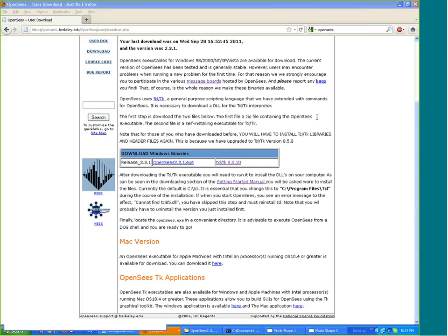Then the next question I have is from Andrew. I noticed the end conditions of the elements are not explicitly defined in the file. Is that part of the different elements' commands? Yeah, end conditions by default are rigid. So if you want to make a pin, then you have to use the equalDOF command. All ends are rigidly connected to each other. So for pin connections, you need to create 2 nodes at the same place and connect them with the equalDOF command, saying that the node that is pinned has the same displacement in x and y as the other one that is rigid, and this way you're creating pins. But if all your ends are rigidly connected to the other ones, then you don't have to specify anything.